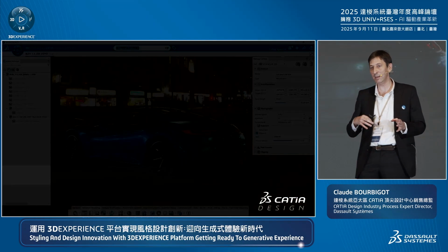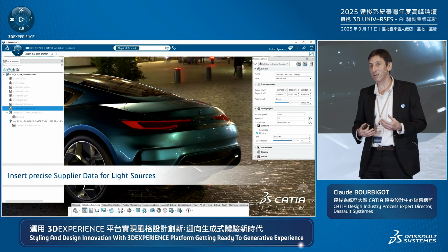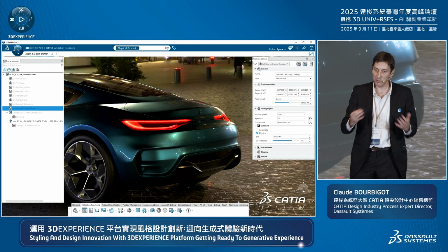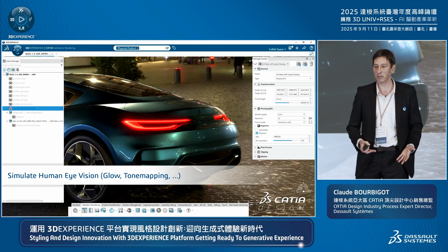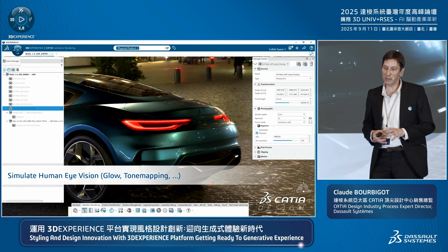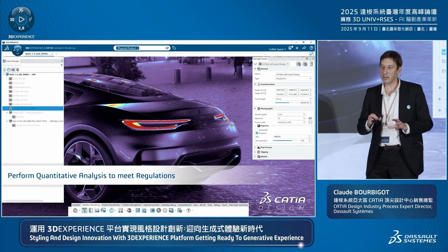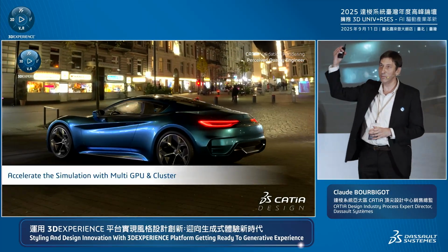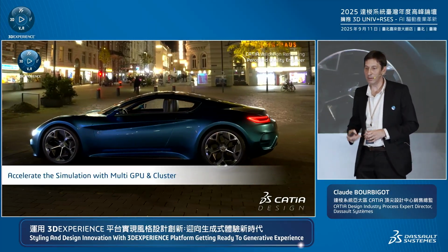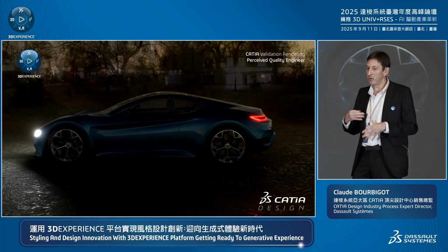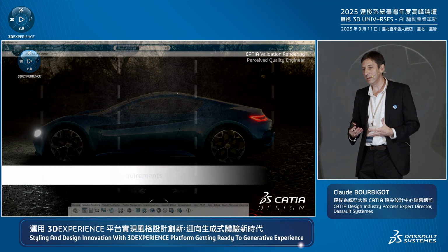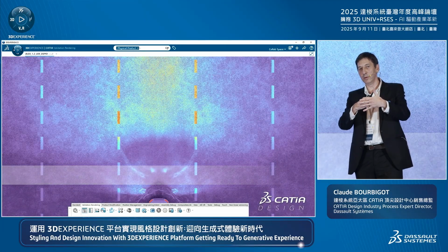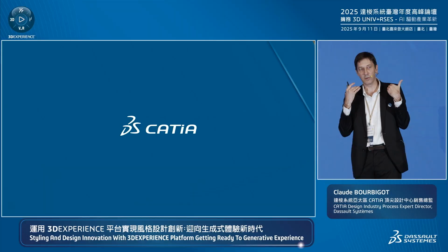What we want to provide is something not necessarily for final certification, for engineers, but more to democratize light simulation to everybody, all our users. Here you can apply physically accurate light units and emissive light materials with units, so you give a lux number to the sun, and we also provide specific algorithms to tone the rendering so that it is more natural to your eyes.